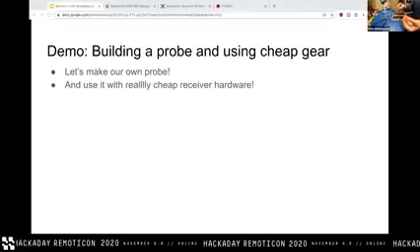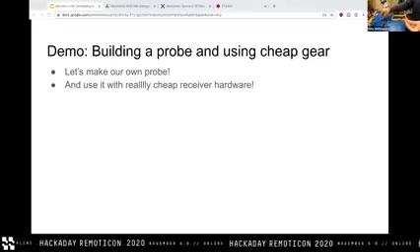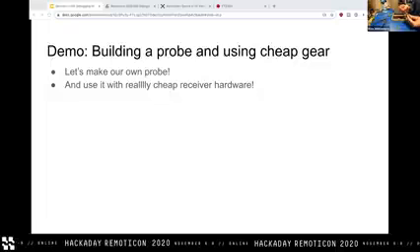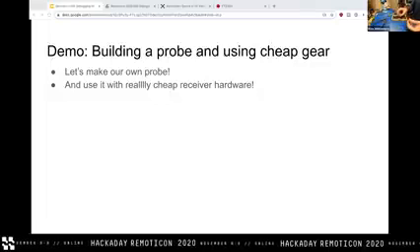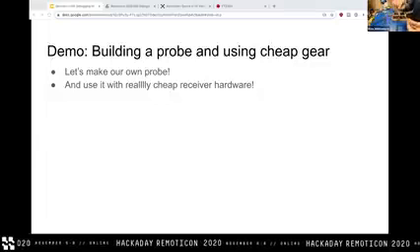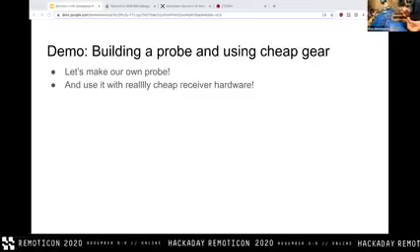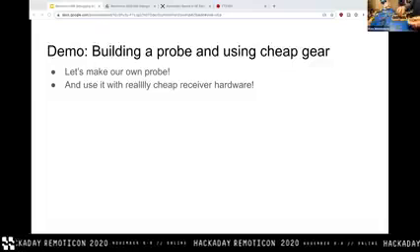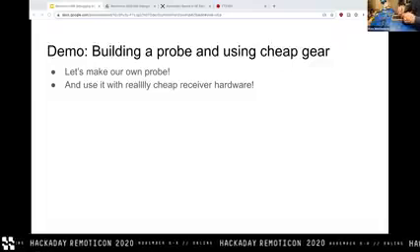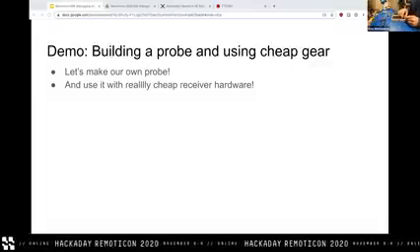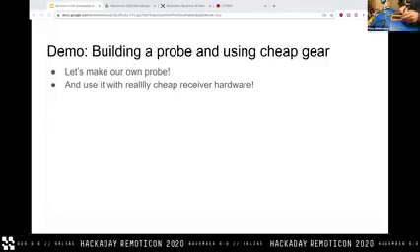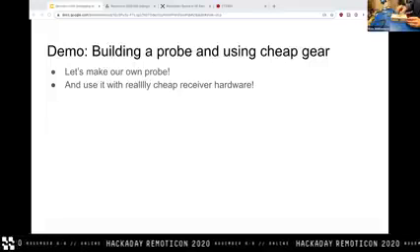So I bought a couple of SMB connectors after the fact and added them, so that I could just use this cable to go back and forth between these two probe sets while I was working. But I encourage, if you're making probes, probably use SMB connectors, you know, with a handle just to make things easy on yourself. But you don't have to overthink it; they'll still work.